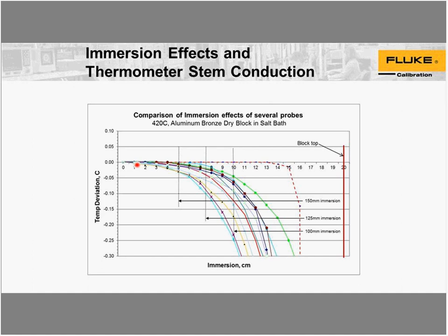Okay, here I've devised a block, and I wanted to eliminate the possibility of gradients in the block, or the limitation of being able to control the various parts of that block to be at equal temperature. I mentioned before, if you've got a heat element at the same watt density throughout the length, the temperature increases till about the center where it's the highest.